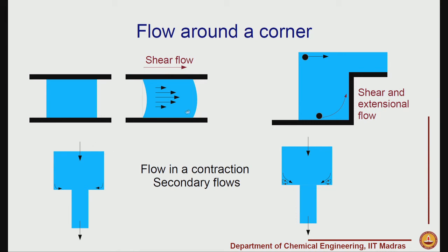So, in other words, if we have two fluids with the same viscosity flowing through here, the amount of extension experienced by the fluid flowing closer to the change in geometry may be remarkably different in terms of extensional strains and strain rates. This is very relevant whenever we have such changes in geometry. In most engineering situations we will have contractions and expansion joints, where the diameter of one section is different from the diameter of the other section.